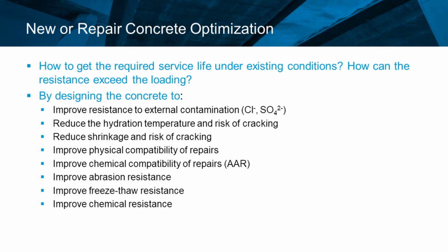Depending on what we want, for example the best chloride resistance, we don't necessarily need to have the lowest water binder ratio. So we can have more flexible mixes with lower modulus that are less prone to cracking, but that still resist chloride ingress. So these things may be evaluated at the time a repair or a new structure is designed.